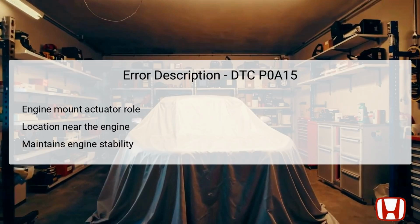The front engine mount actuator plays a critical role in stabilizing the engine by adjusting its position as required during various driving conditions. It is situated near the engine, directly connected to the engine mount control unit. This unit processes data from sensors to ensure the engine runs smoothly, thereby minimizing harmful vibrations that can be felt inside the vehicle. A malfunction in this actuator could lead to increased engine vibrations, which not only affect ride quality, but could also cause long-term damage to associated components.